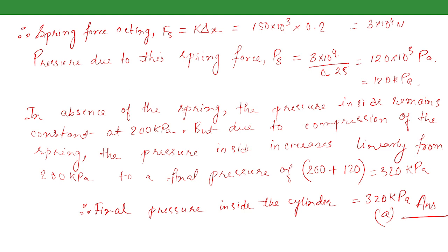See, we are considering a linear spring. Okay, that is the force is a linear function of the displacement. So since it is a linear spring, the force due to it will also increase in a linear fashion due to the displacement. So the resulting pressure will also increase in a linear fashion from 200 kilopascal to 320 kilopascal.